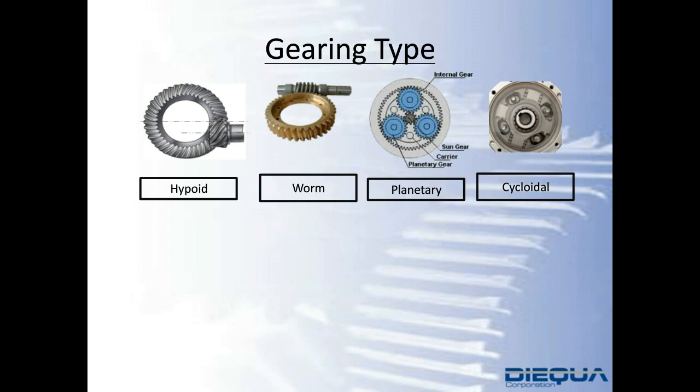This output connection we've been emphasizing is a robot flange, a rotary output, if you would. And that would be advantageous over having a hollow keyed, a hollow shrink disc or a solid output shaft, whether keyed or round smooth.